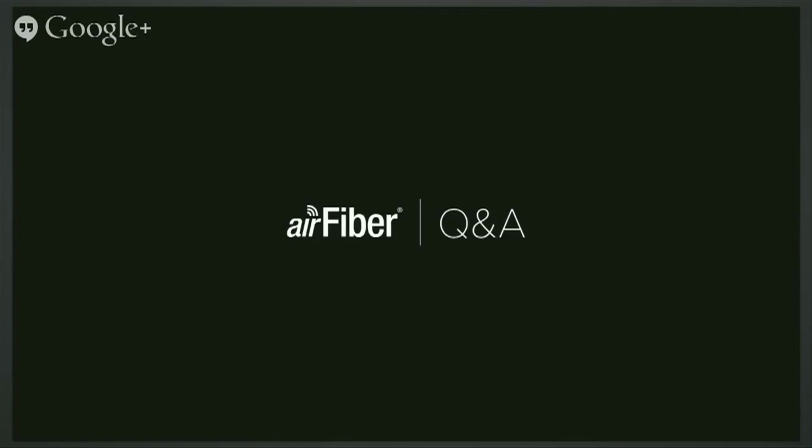People think about, well, we pick up a lot of noise, and the receiver may be picking up noise, and maybe that's why we can't hit that. But the transmit side also has to have really good signal integrity, and the way you get that is with very linear power amplifiers. Unfortunately, for those of you who are familiar with radio design of OFDM radios, you end up having to have a fairly wideband amplifier that is very linear, and almost by definition, those things consume a lot of power.